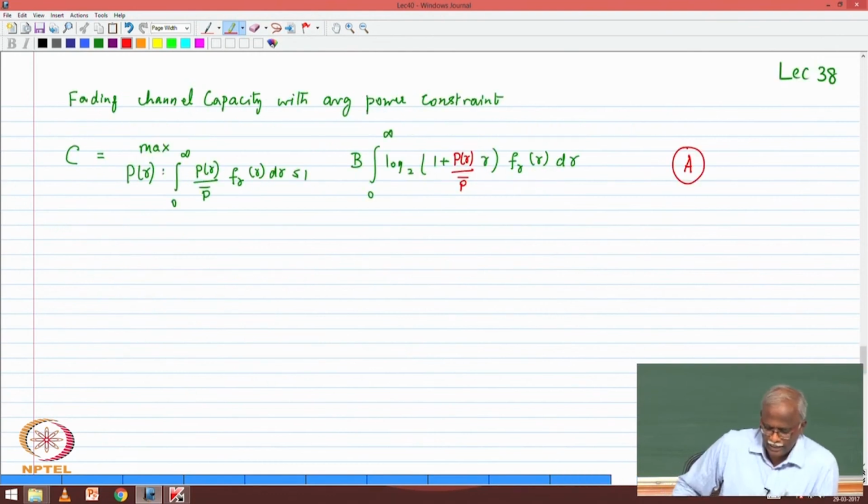So the statement of the problem that we now have is, I want to maximize capacity under optimum power allocation. So the power allocation, if you denote it as what we have indicated in red as a normalized coefficient, either boosts gamma or decreases gamma. That's the decision that you have to make.